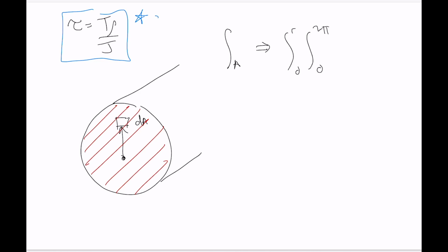Okay, so it's only for circular cross-section. And I know formula derivations are sometimes hard to sit through, but they do tell you a lot about what a formula can and can't be used for. So for instance, in this case, we know that it can only be used for a circular cross-section because that was built into the derivation of it, and it doesn't apply to things with rectangular cross sections or triangular cross sections. We don't often see those being loaded with torques, but sometimes they do occur.